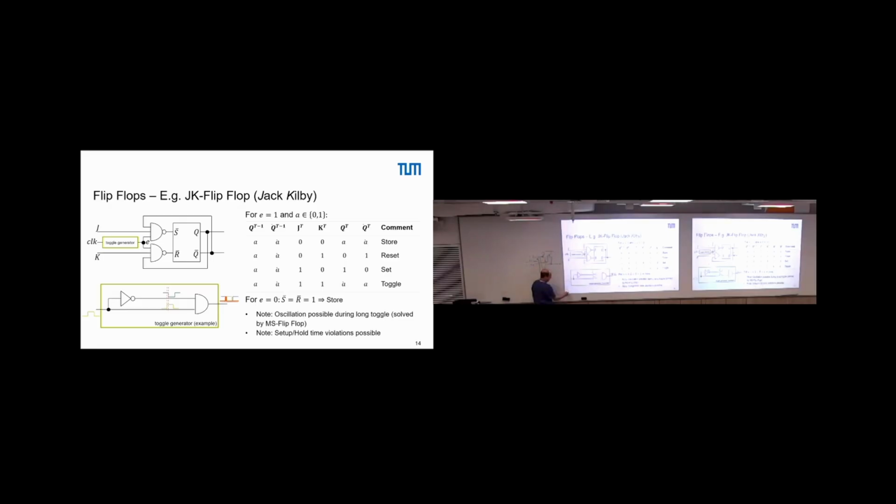So, yes. So, this is always my personal helper. If here is a 0, then this here should be shorted, right? So, that would mean if you connect it here, there's a short circuit, right? So, no, that we don't want. What do we want? Well, we want to implement a truth table, right? Now with A, B, C, out. I just write maybe first this one here.